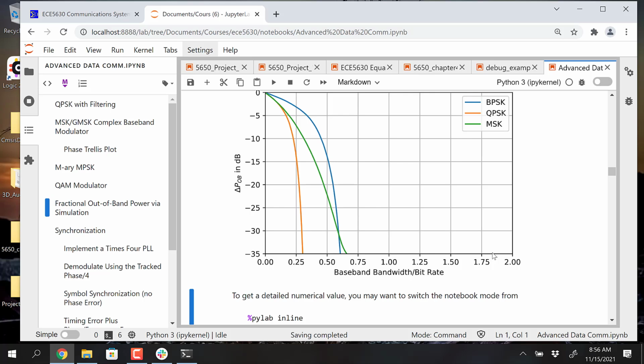They just broke the rules. What rules did they break? Well, the rules that they broke were in the beginning, SATCOM required and was desired to have constant envelope because of nonlinear power amplifiers in space, and they wanted to have as efficient a power amplifier as possible to save on battery and weight, and they didn't want to go with non-constant envelope. So that's why these things are still talked about.